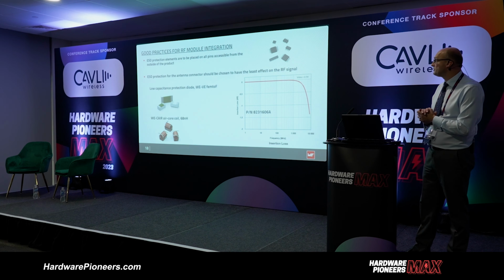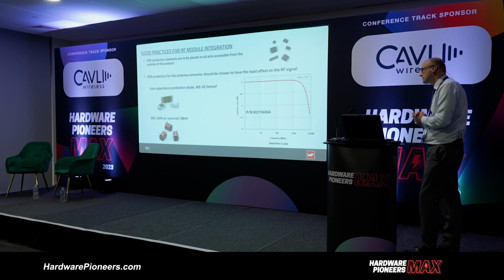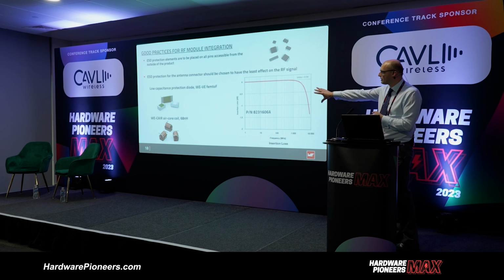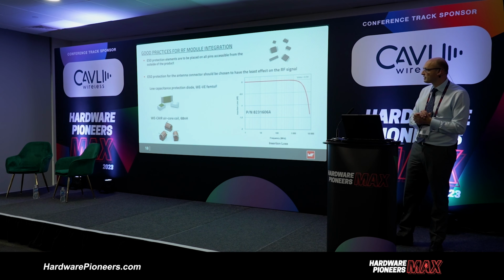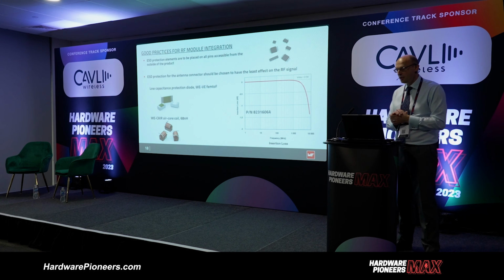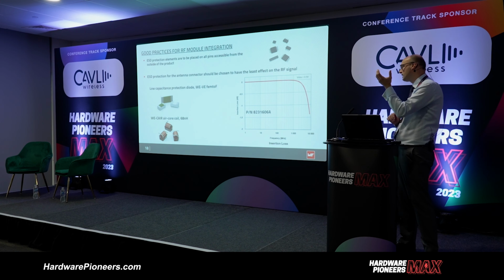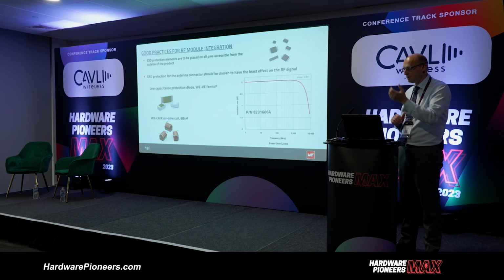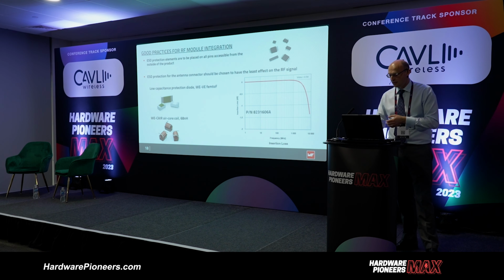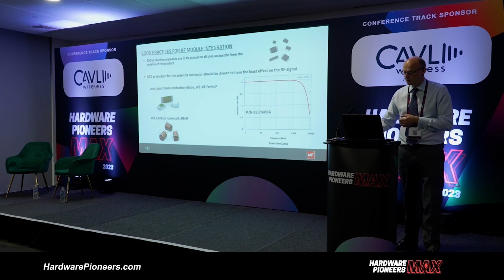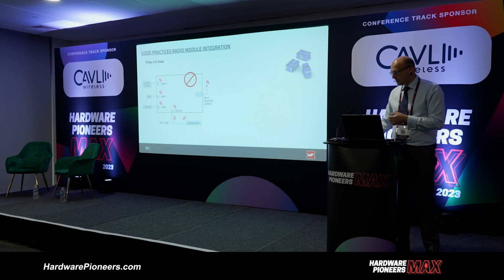Another way of reducing ESD, not as effective, and once again this comes out of our application notes and user manuals for our modules, is the introduction of an air core. In fact, you're just putting a high level of inductance in there to the ESD pulse to in effect slow it down from going into the actual product. So it's not as effective as an active ESD protection device.